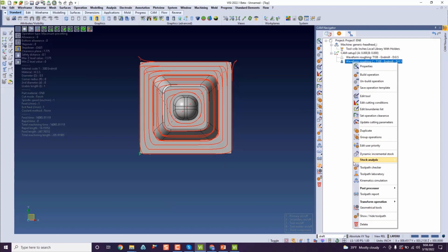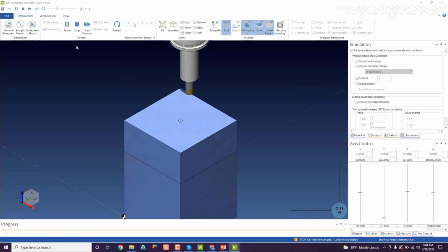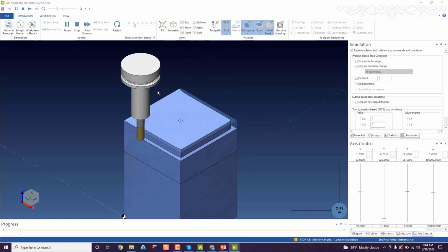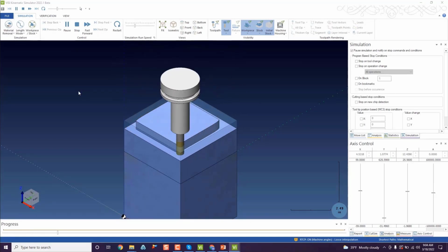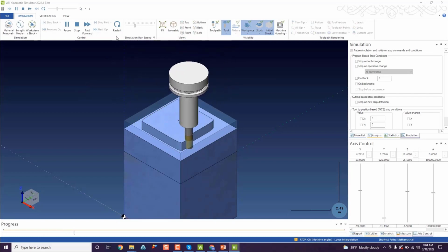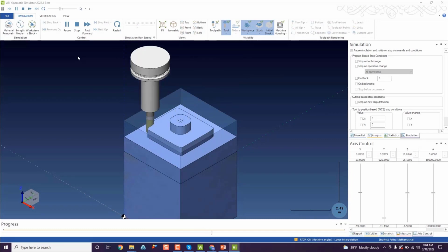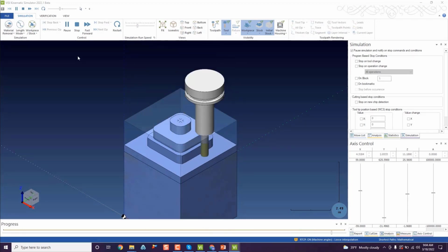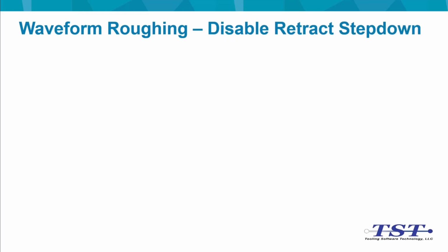Now this will help the user save on the life of their tools and avoid working with plunging operations. Avoiding the helical, you can also save on machining time. That means the tool is not taking more time to spiral into the part. It is actually able to get to the depth that it needs a lot quicker.